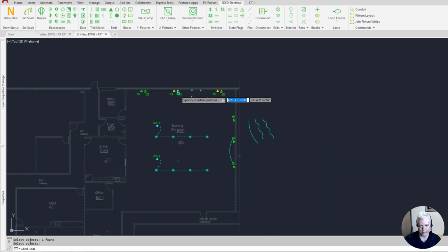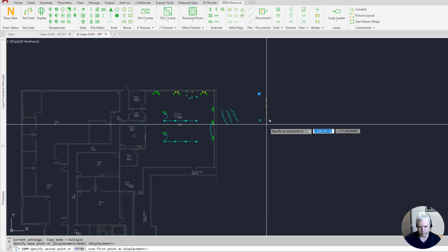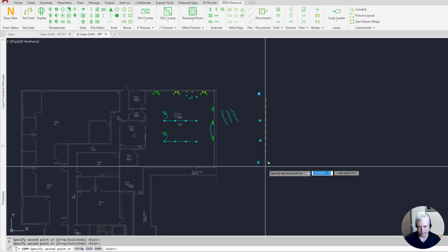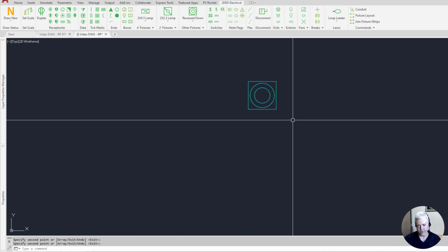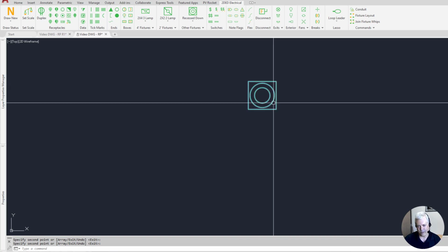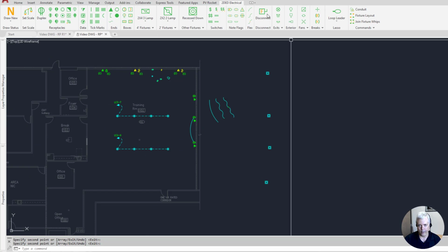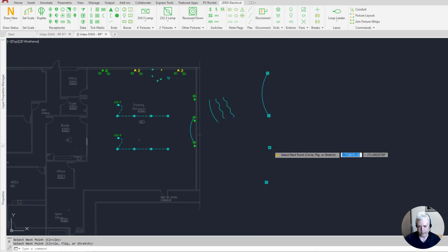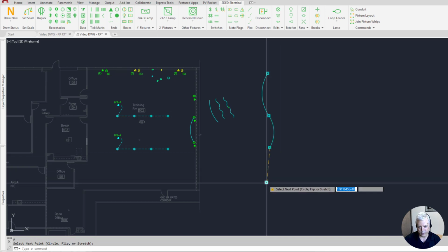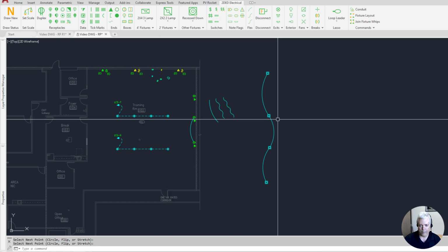Let me show you an example. I'm going to put this downlight symbol, I'm going to put 4 of them out here. See that there's 2 concentric circles inside a box. Let's say I want the circuit drawn to the outside circle. Okay? I'm going to use that arc and go from here to there. I'm going to flip it so that it gets kind of wavy. We like waves here. And press enter.